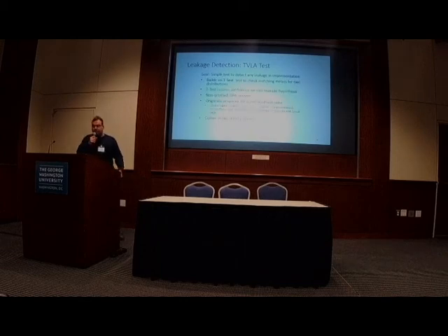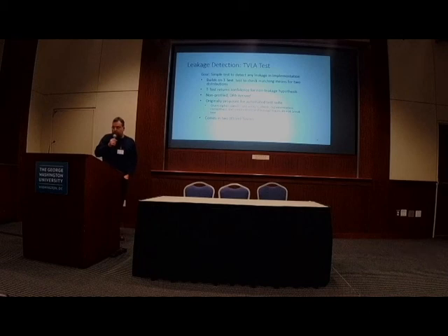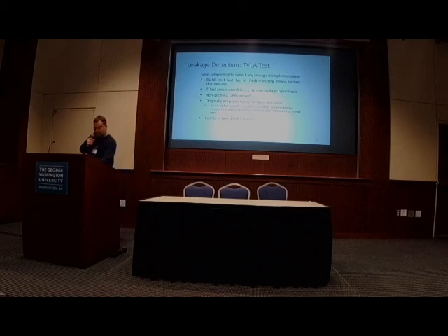And then finally, the TVLA test has been pretty successful recently. I'm just out of time, so I'm not going to go into it. But it's an adaptation of the t-test to the device under test model, for side channel quantification. The graph I've shown you before of the threshold implementation of Simon is an example of that, where you have the data sticking out beyond 4, right?